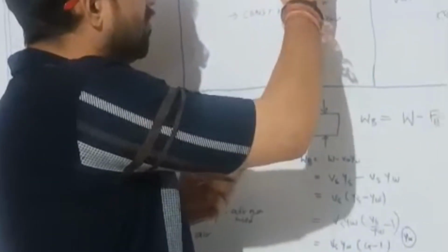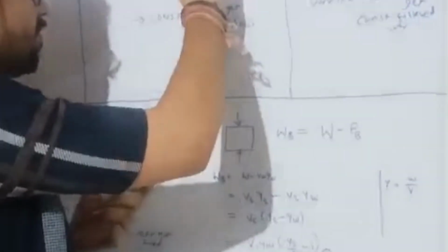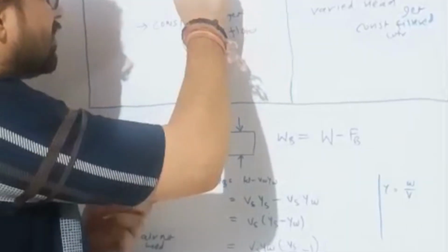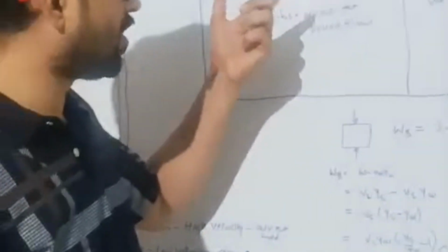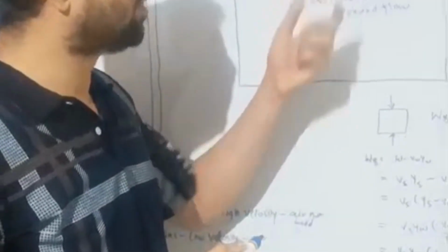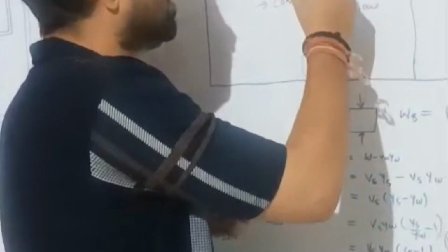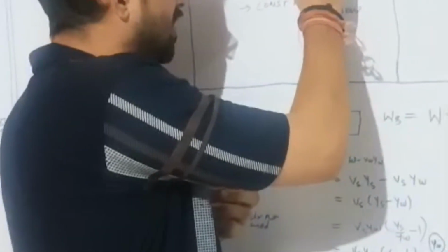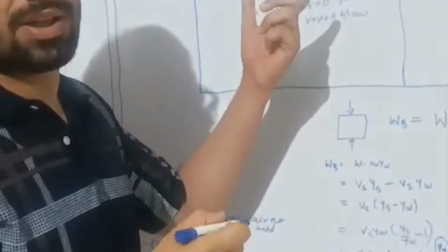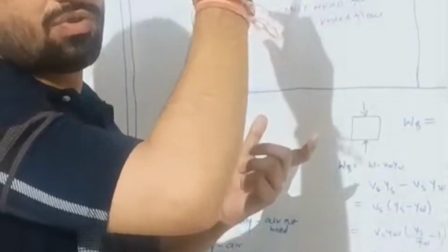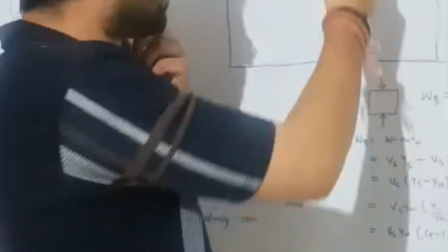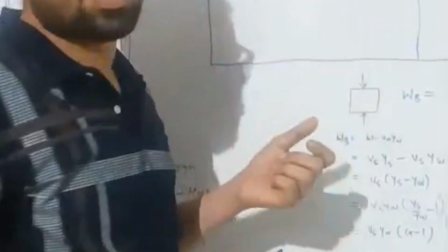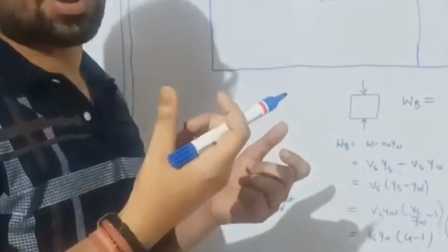When the water goes through the filter media, impurities get entrapped in the voids. When the impurities are entrapped between the voids of the filter media and the gravel media, the static head resistance of the filter media and the water head required over the filter media become equal, and vacuums are created over the filter media. This is called the negative head.